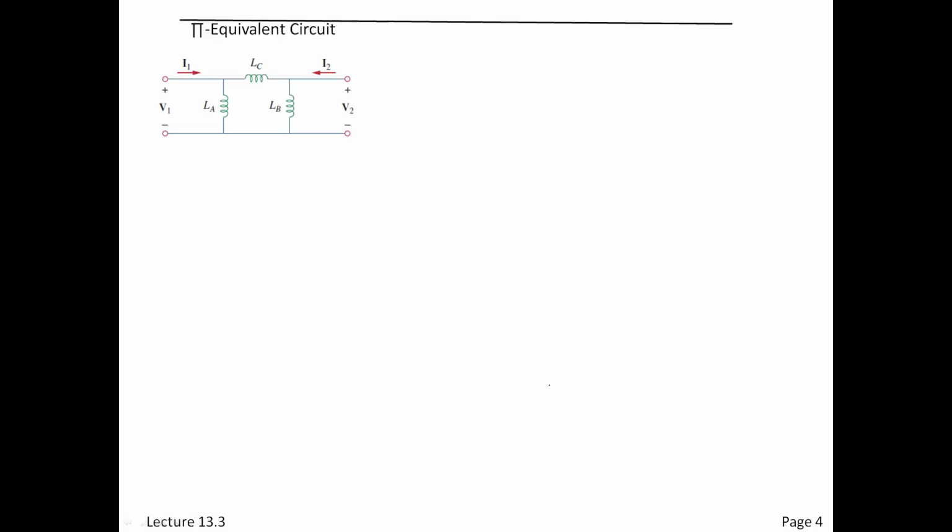We call this the pi equivalent. These, by the way, are common pictures that we're going to be encountering later when we make equivalent circuits. So the pi equivalent now is this, and notice again, the same variables apply in the same direction at the terminals. All right, and this one, if we do this as currents, so what are we going to be doing? We're going to be using this form of Ohm's law, V over Z, right, and find currents everywhere. And if we fill out the matrix, this is what we're going to get.